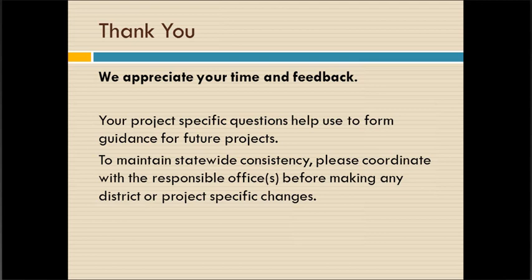All right. Is any consideration being given to segregation of 2-4 skip and 6-10 skip? This will make quantifying easier. I'm not sure exactly where you're talking about the segregation being. They are both lumped into the same pay item number, but if you draw them using the DNC manager, I've got that set up for 2-4 and 6-10, and the units are set up for the different stripe lines, so you should be getting the right quantities.